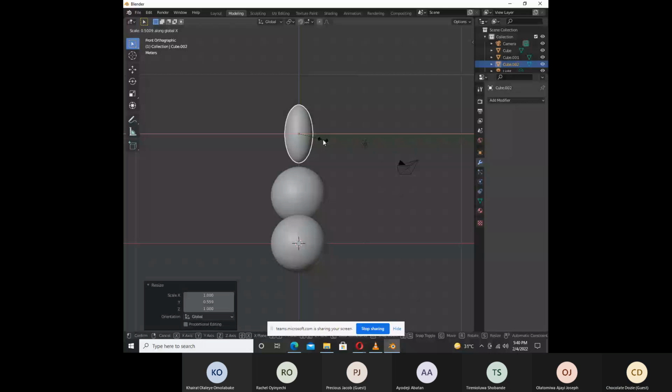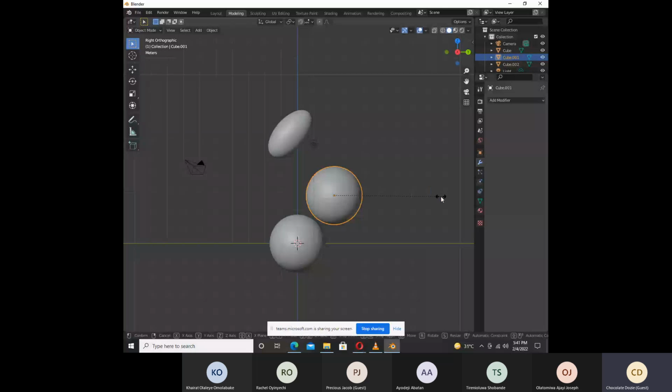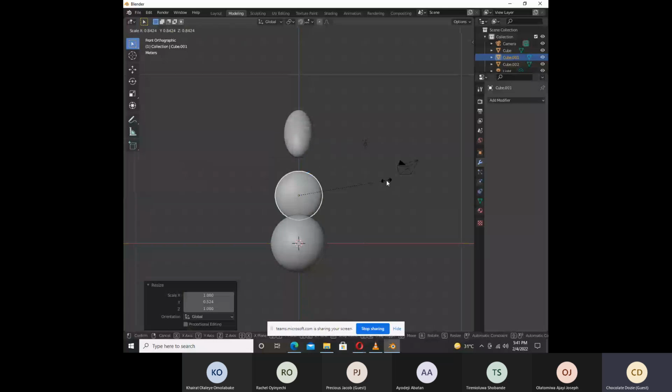All right. I'll rotate to tilt at maybe 45 degrees. Then I'll come to this one. This one will give us the upper neck segment of the horse, or of the knight piece. So I'll scale this in the Y axis a bit and go to the front perspective and scale it in the X axis. All right.